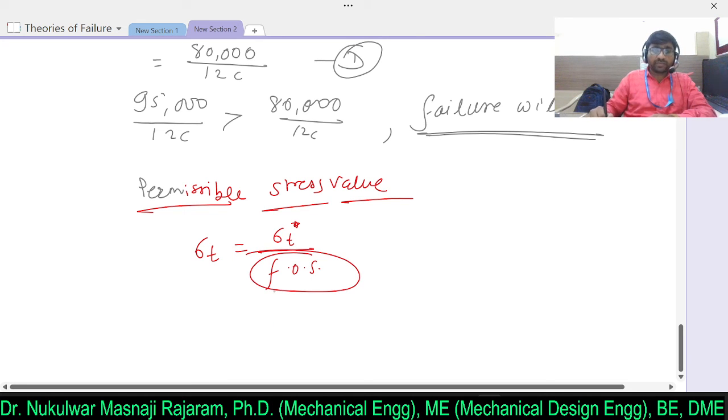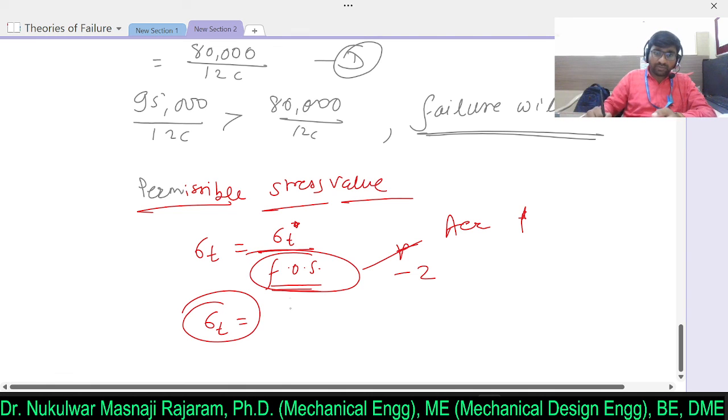This factor is very, very important, and in aerospace and similar fields, we increase the factor of safety. Clear? Due to this factor of safety, we design the entire system on this sigma t. So if I consider a factor of safety of 2 for the same numerical, then I will design the entire system on sigma t equal to 100 Newton per mm square.